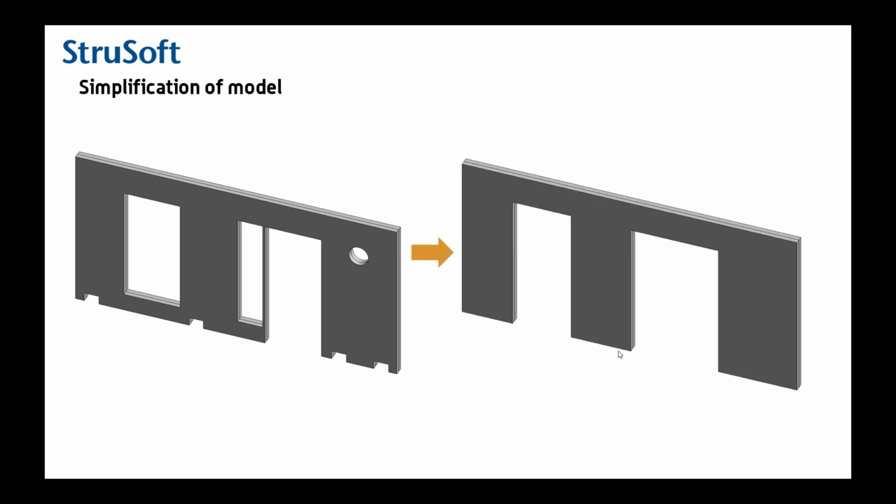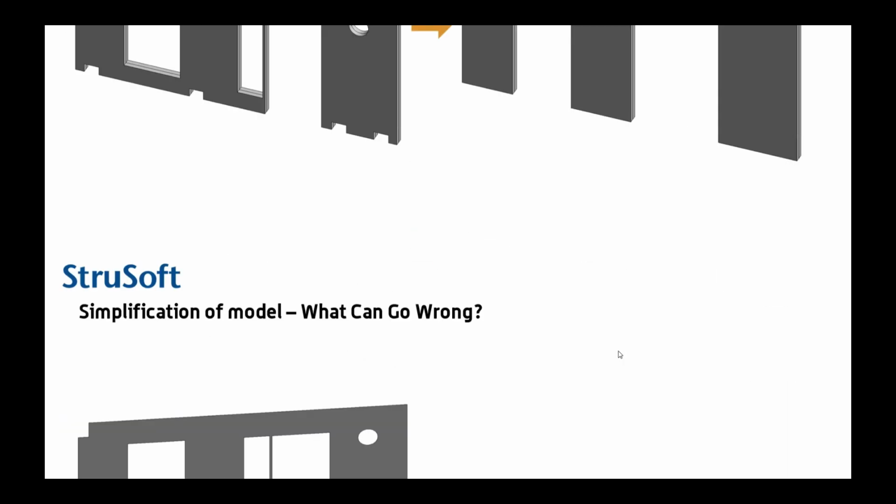And the first step we usually take is the simplification, and I always recommend that you do the simplification first. So this is our raw model. It has the element connections and also a lot of holes and thin parts, and we simplify it so that this is probably what we want our finite element model to look like.